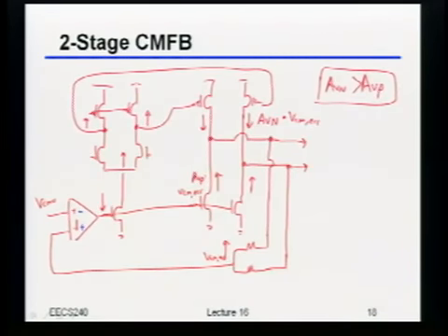Okay. So let's see. Maybe we can tease it out of somebody. So somebody who said that AVN is greater than AVP. Why is that? Why do you think that? I tend to agree with you, by the way. It passed through more gain stages. Yeah, right? So basically, this AVN over here gets gained from this point to that point.